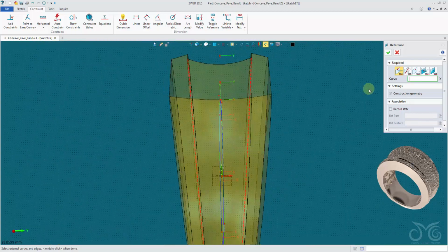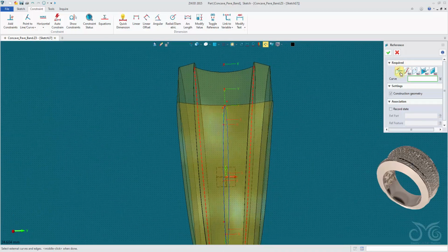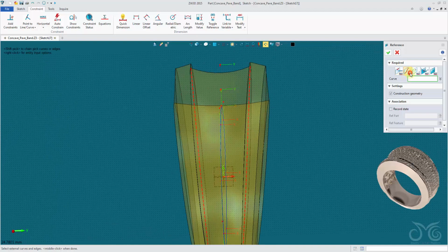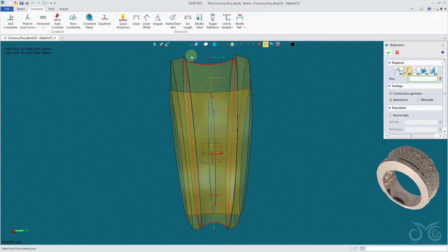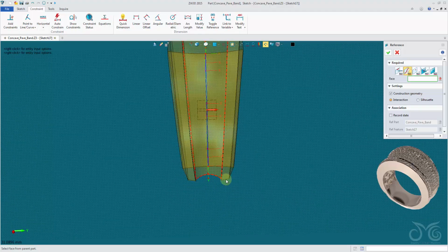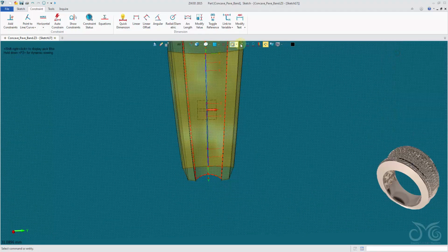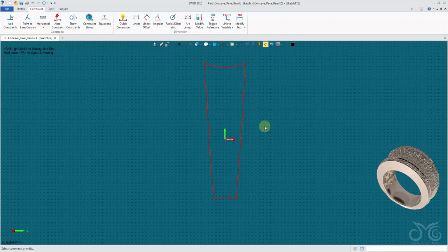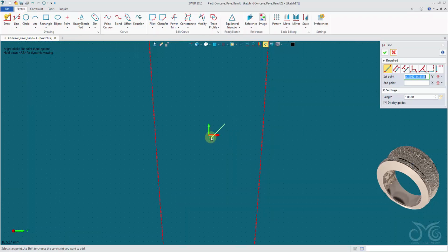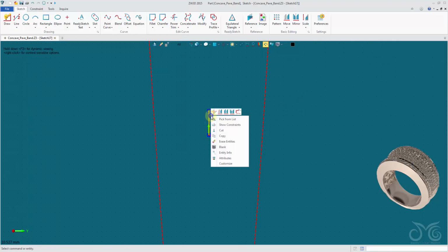Okay, using our top method. Then I'll come in to the face reference and reference the concave face. Okay, so we get the top reference line and the lower one. Let's exit out, show target, plane view. Okay, now we can come in with a simple sketch that we'll use to separate our surface. I'm going to place a line from here. I'll set this to be construction geometry.